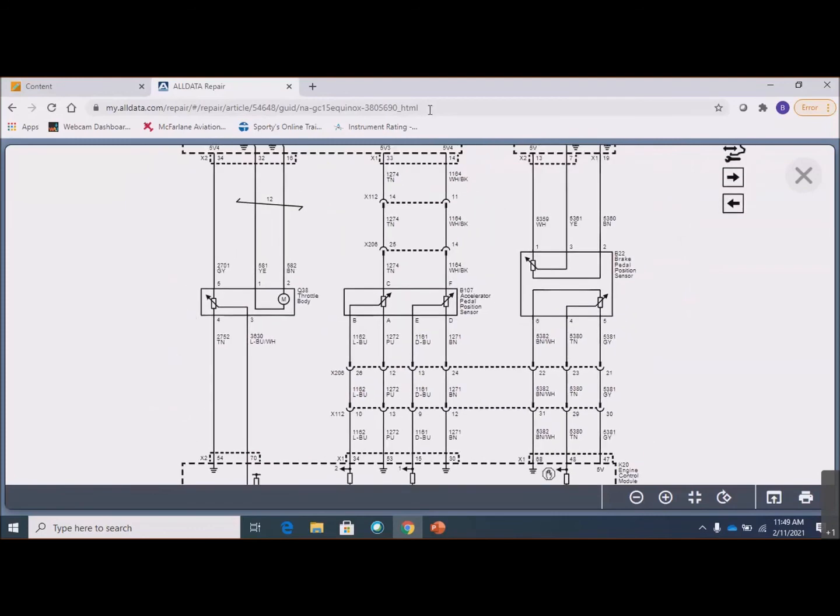The other piece here, built into this throttle body, you might notice, right? Pins 3, 4, and 5 have nothing to do with moving the throttle plate. What is that? Well, you can tell it's the same as this. It's the same as this, right? In fact, here's a couple more. These are potentiometers. These are position sensors. So where this one here is an accelerator pedal position sensor, and so is this. This one here is a throttle position sensor.